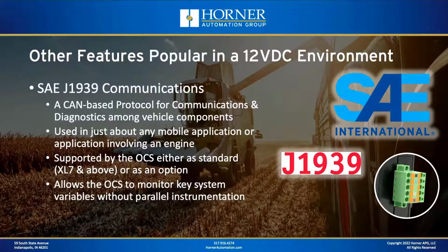So the OCS is perfectly capable to monitor that data as well as to perform some level of control over J1939. Now, one of the requirements is you're going to need to have a copy of what they call the PGN list, which is the parameter list for the engine or the device that you're monitoring over J1939. Not all manufacturers are that open with supplying or publishing that list. However, a lot of the parameters are common, not different from manufacturer to manufacturer. Therefore, if you can come up with a PGN list, you can probably find the data that you're interested in and be able to monitor that from an OCS over J1939. So definitely a popular feature for sure.